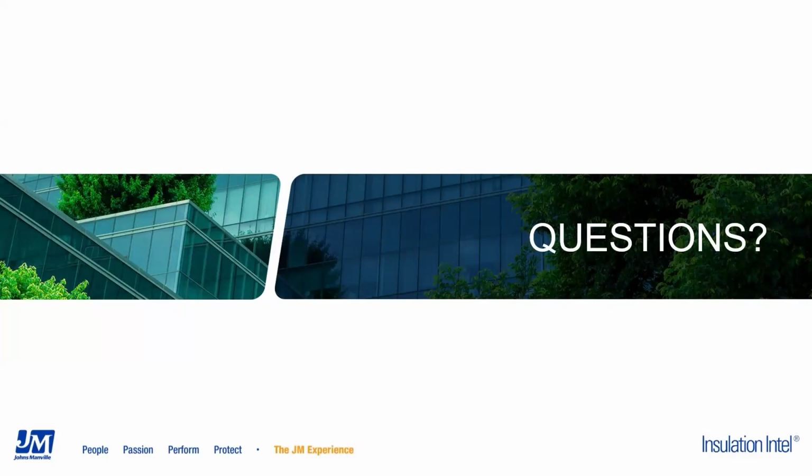Next, we have: when increasing wall insulation R-value, are improvements added? Yeah, I pulled up that question window too, so I'm seeing that. David, I think maybe what you're asking is about the table that I showed, with the different R-values for wall insulation. At least for homes, it was more upgrades versus added, right? So it's more like insulating your wall with R19 instead of R13, and then realizing those savings from making that substitution, I guess, is the better way to describe those versus an add.